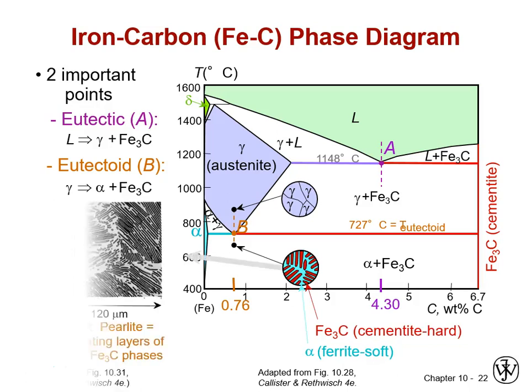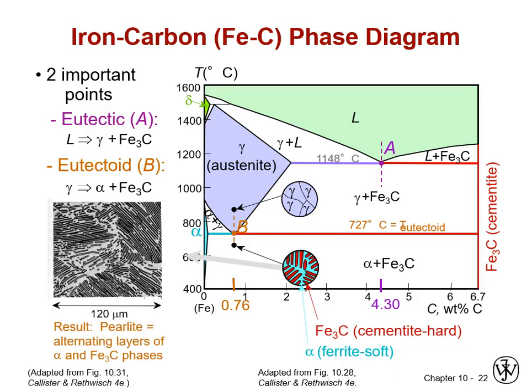And just stepping through some microstructures. If we look at eutectoid steel, cooling something down from somewhere in the austenitic regime at our first black dot that we showed, where we have all gamma phase, single solid phase. If we drop down through the eutectoid temperature, much like we did with the eutectic temperature in the lead-tin phase diagram, we suddenly form the eutectoid, which looks very similar to eutectic. We've got another lamellar structure.